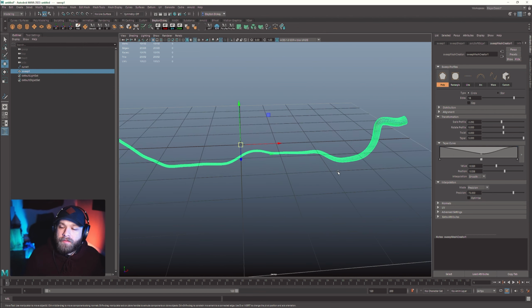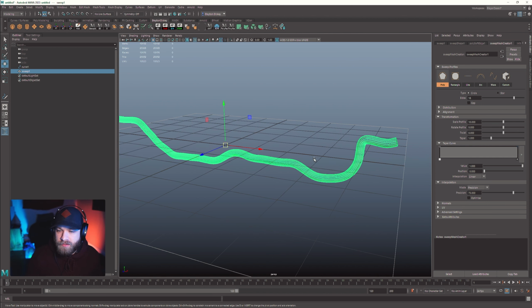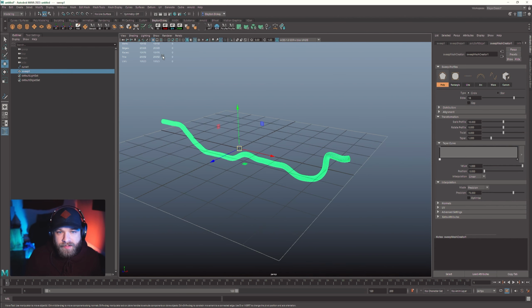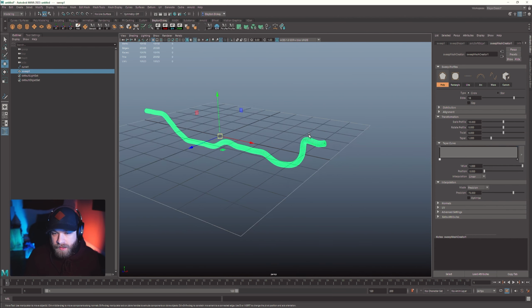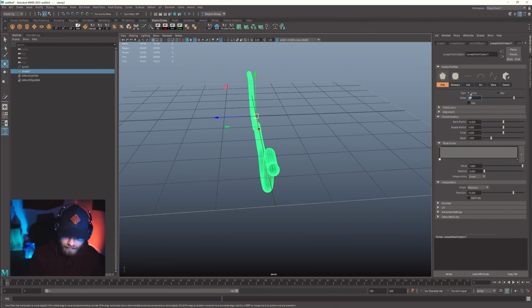So again, that can be a really nice control functionality to be able to get in there. The last thing that's really going to be nice is the ability to dial in how many points are being used to make up this curve. Because right now, this is 20,000 triangles, which is a pretty dense curve, and may not be necessary for what you're looking at. So we can go down to like 8, or let's actually set the sides to 6 here.